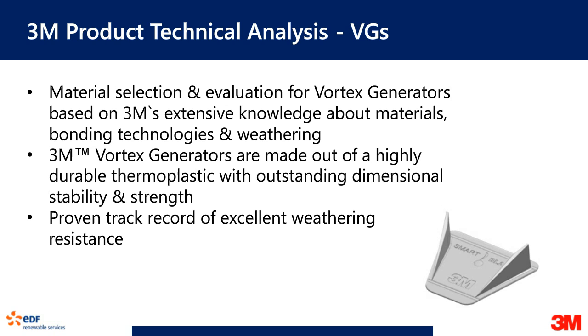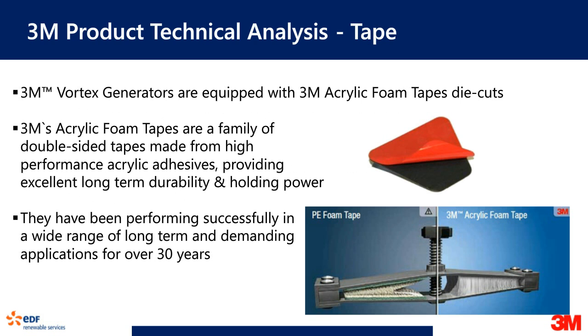The first thing is you need a vortex generator that doesn't age very quickly. So you need to select the right materials that will actually last long. Our weathering capabilities that we have over many years really helped us to figure out which is the right material for this application. The second aspect of it is you need to understand how do you attach it. Most of the time, when we started looking at this industry and how to fix this problem, we started with adhesives. We started with different adhesives to say how do we optimize the application and how do we extend the life of the vortex generator.